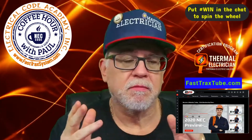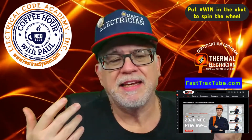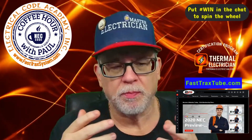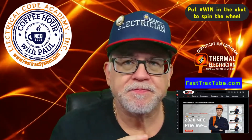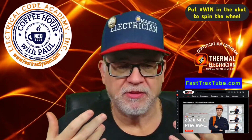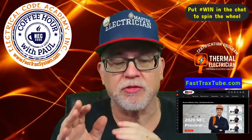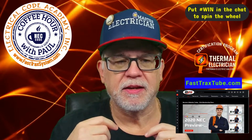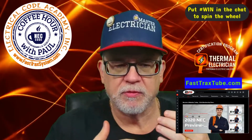Now, for a lot of electricians, they're thinking, well, if I do residential work, what do I need to care about thermal imaging? Because even NFPA 70B says that you need to have at least 40% loading in order to get any reasonable values. Ideally, we want things running at normal rates. So usually we will train that the thermal technician or the thermal electrician will actually turn on things during their inspection, like the ovens and big appliances. They'll turn these things on and take readings as part of a process.